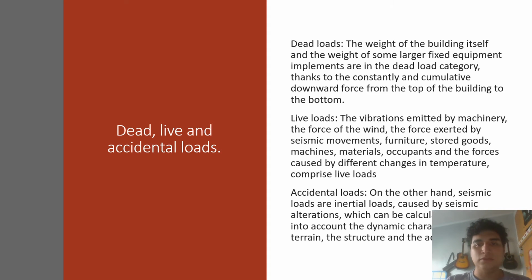Then we have the live loads. The vibrations emitted by machinery, the force of the wind, the force exerted by seismic movements, furniture, stored goods, machines, materials, occupants, and the force caused by different changes in temperature comprise the live loads. These are all of the forces and loads that the building must support, given by all of the environment we have in it and its own equipment. Like in a classroom, all of the students that are there are live loads.